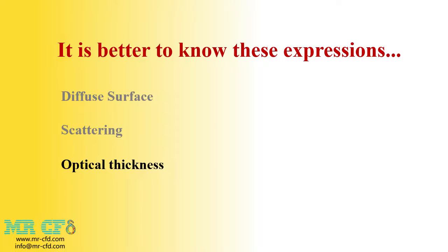And about optical thickness. Actually, it is a measure to check the ratio of incoming or incident radiation to transmitted radiation. The thicker this optical thickness is, the more radiation it receives and the less it passes through, so the light is easily absorbed, while the thinner it is, it receives less radiation and passes more, so the light passes easily. Participating effect, actually basically any medium that absorbs, emits or scatters radiation is called a participating medium.